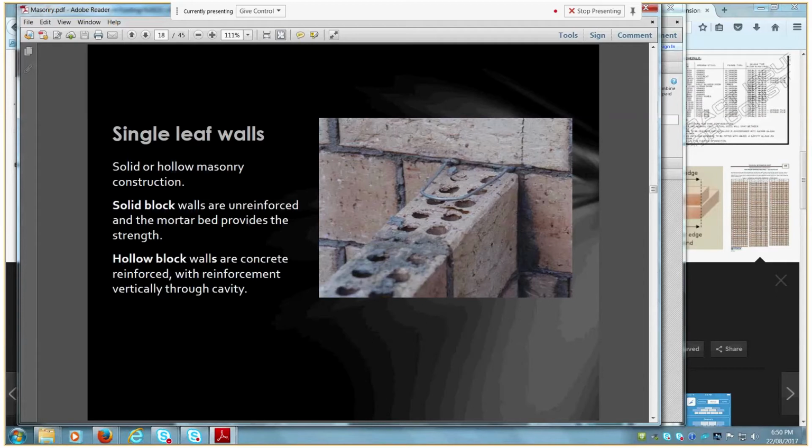Because if we carry that through as single leaf masonry all the way, then there's little to resist the overturning of our single leaf masonry. So single leaf masonry has to be tied into other walls or have engaged piers. And the way those engaged piers are constructed are like our other forms of double brick bonds.